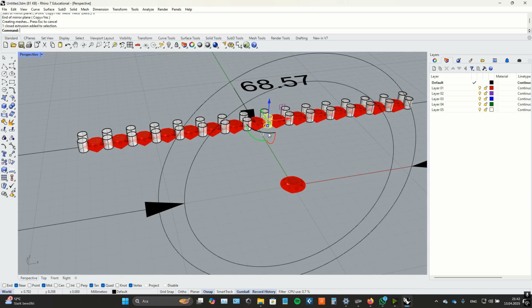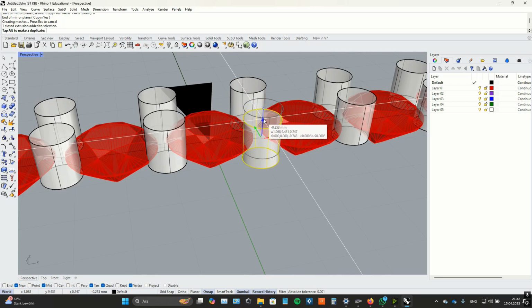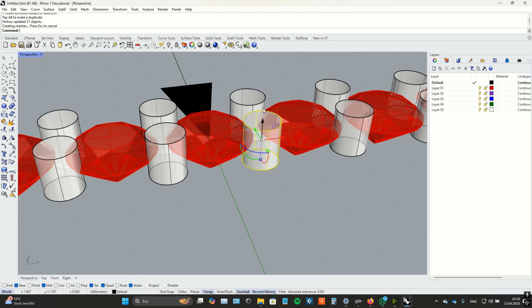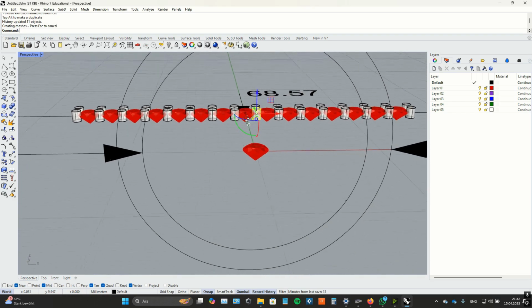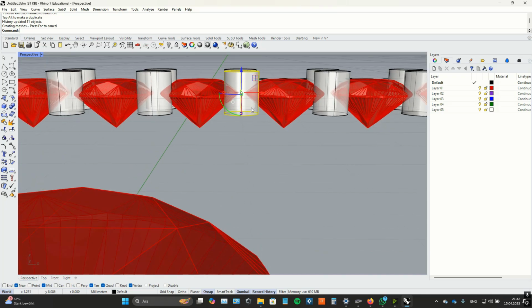So this means if I move this prong down a little bit, let's say we'll want to drag it down to minus 0.30 millimeters. Enter. You see everything else, all the other prongs are updating. That's very practical. Nice.